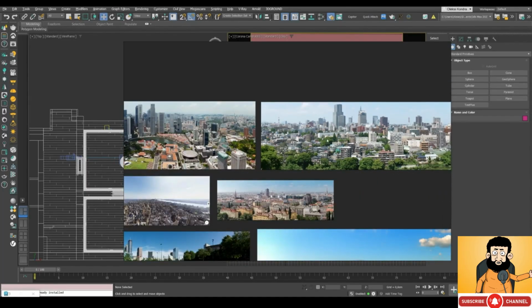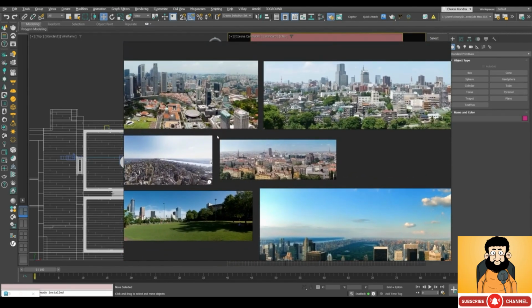Now, the next mistake on our list is an incorrect horizon line. We're going to see that during the practical part, but in short, the horizon line in the camera, the horizon line in your background, and all perspective lines must meet in one point on the horizon. If you follow this rule, you'll never end up with a distorted perspective. It's not uncommon that the background is put too high or too low, causing the perspective to look broken or distorted, and as a result, you get a sensation that there's something wrong with the render.